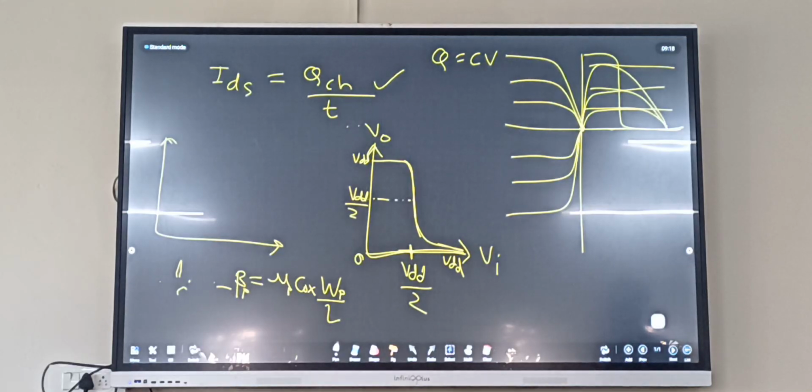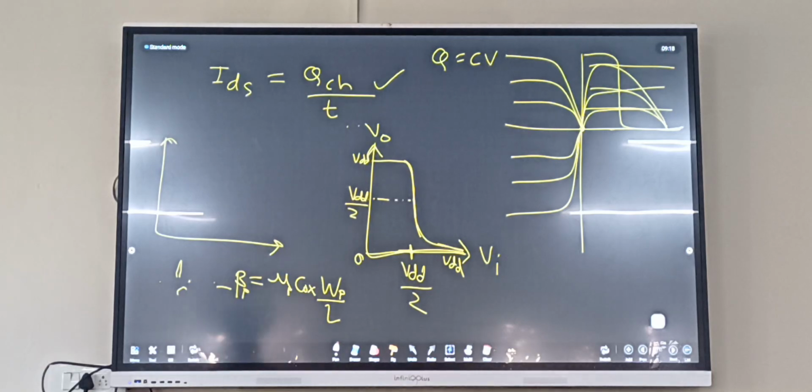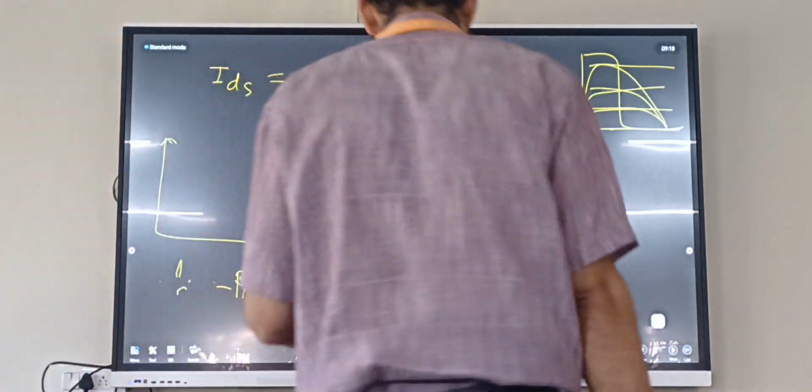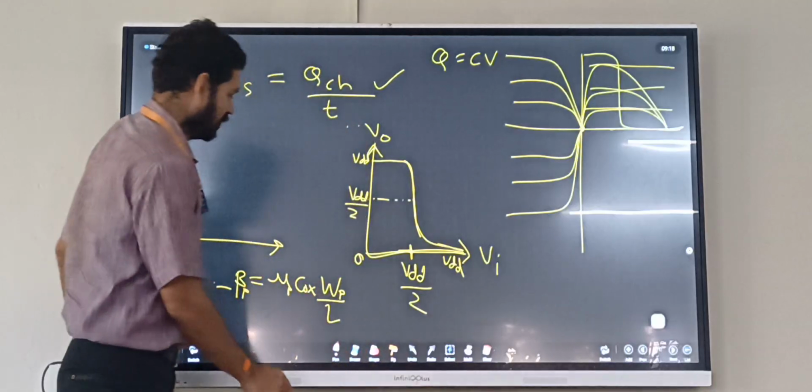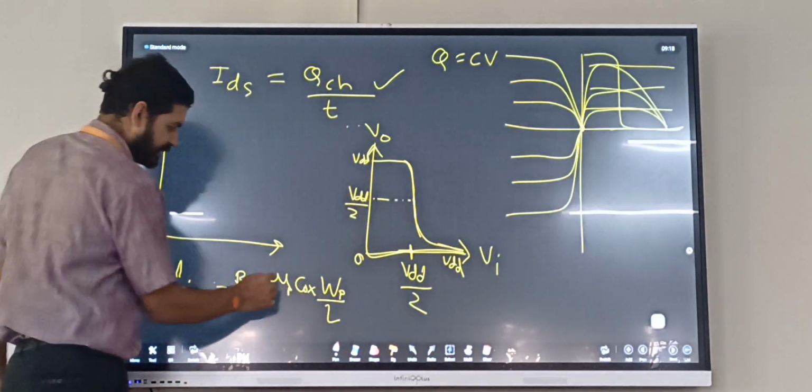It is a GPDK technology which we use. If you are working in 90 nanometers, you will work in 90 nanometers; you can change the width, but you cannot change the length. Lengths are fixed. So width can be changed. Fine. So actually, this is a constant.